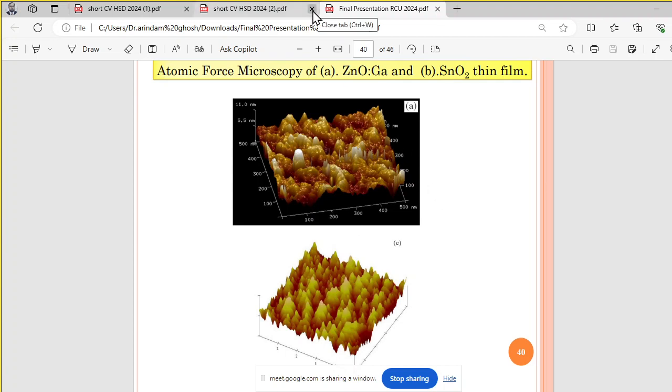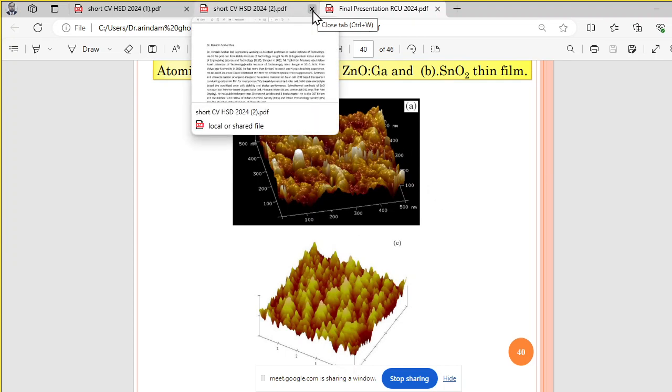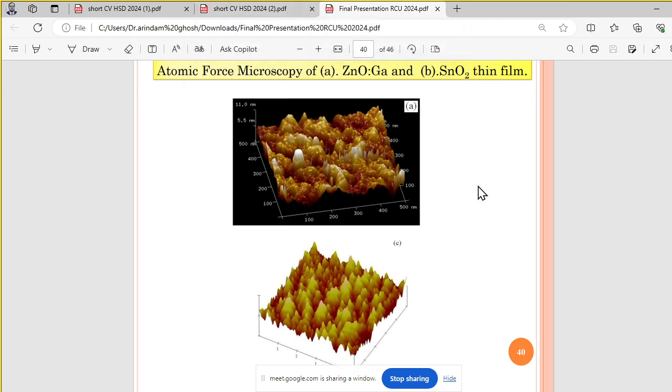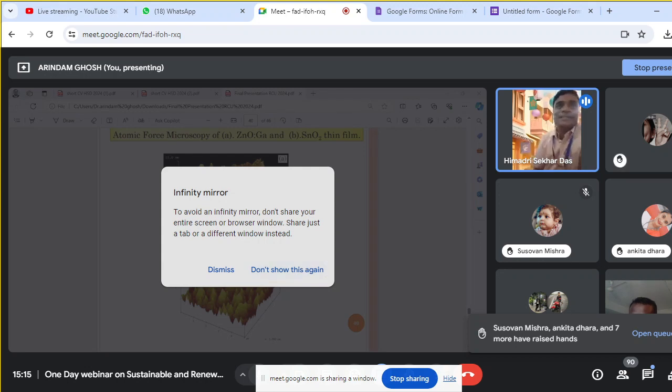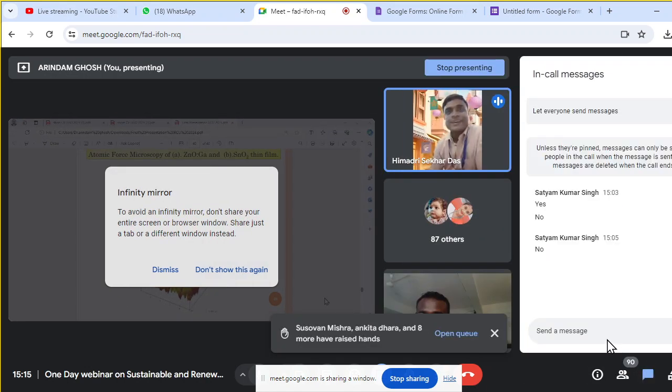In OLED fabrication, the anode material surface should be as smooth as possible, because some roughness means there are some spikes. It can be clearly seen from the AFM that many spikes are there. These spikes in the anode layer may cause a breakdown or shorting of the diode, which in turn reduces the stability of the device. So a smooth electrode surface increases the lifetime of the OLED.